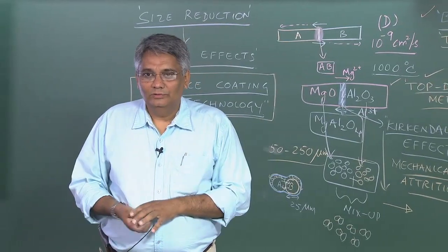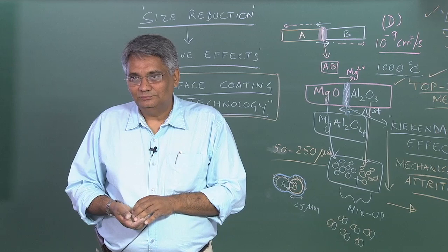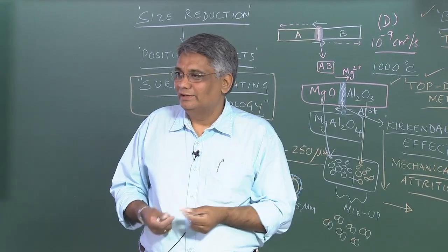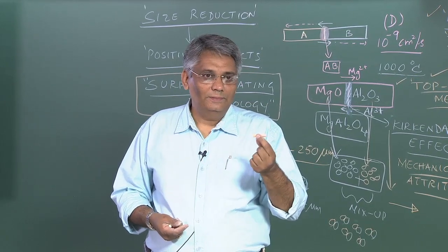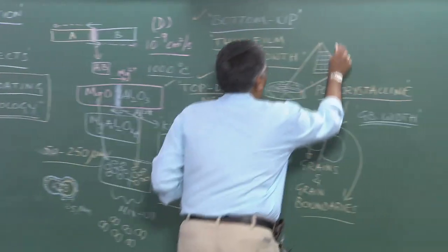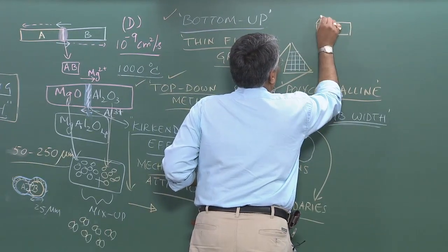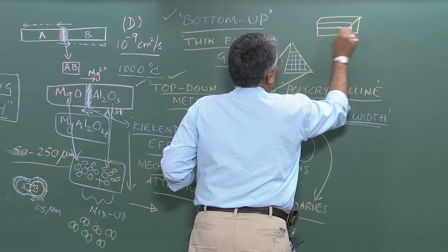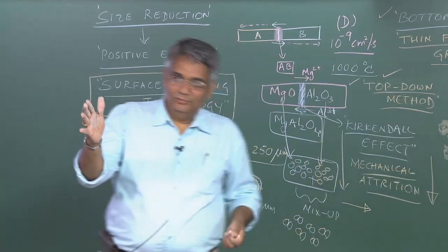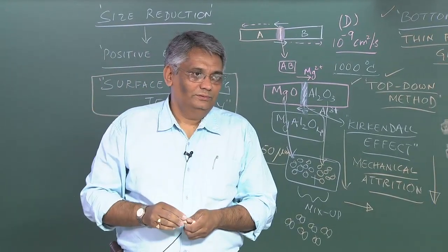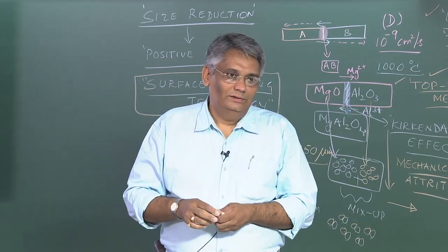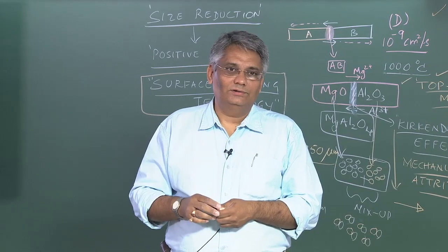But if you convert this polycrystalline material into a single crystalline thin film, right? So you can avoid the formation of grain boundaries. If this solid material is called a single crystal, how many grains would it have? It will have a single grain, right? So if this is a solid I have, and I call it a single crystal, then from this end to that end, I have a perfect periodic arrangement in all three directions without any atomic termination, defects, etc.